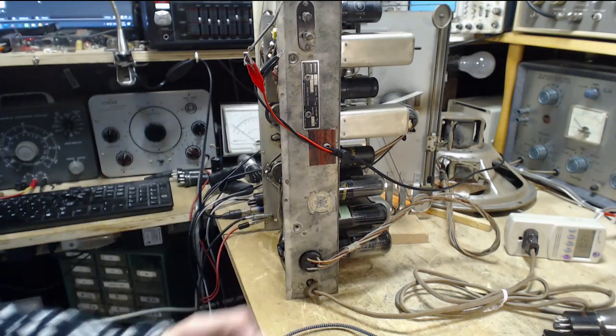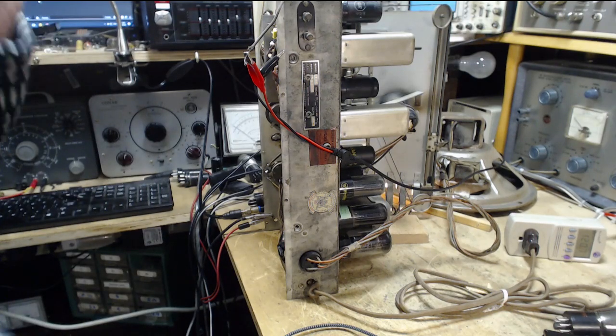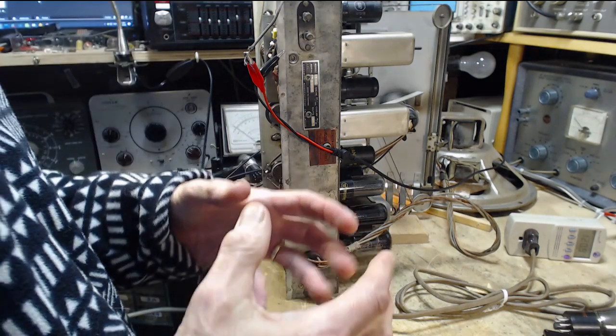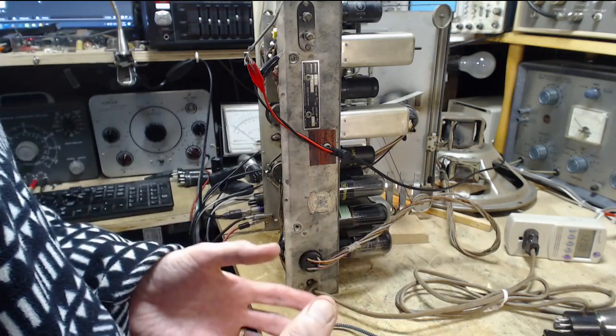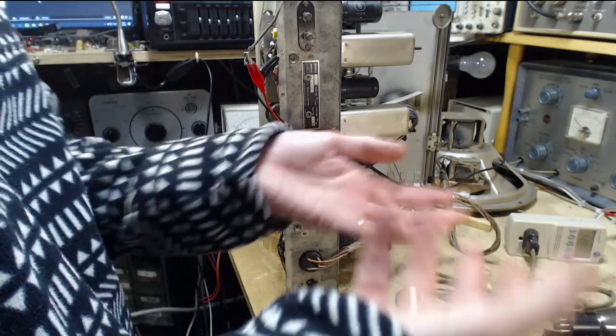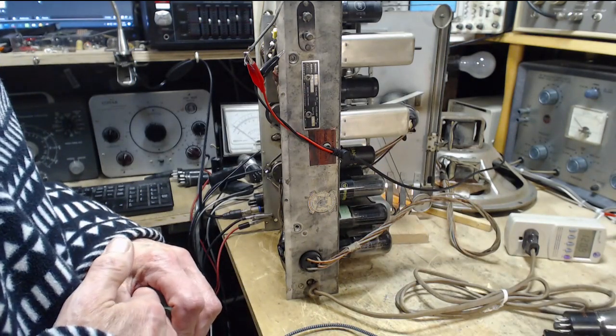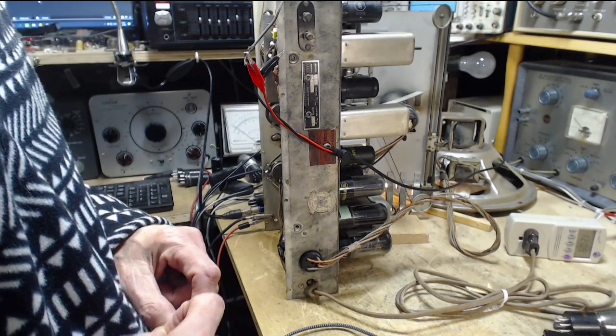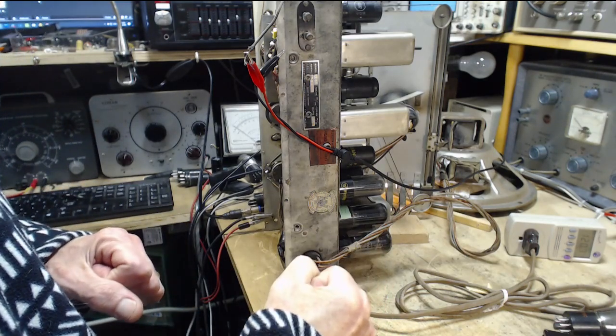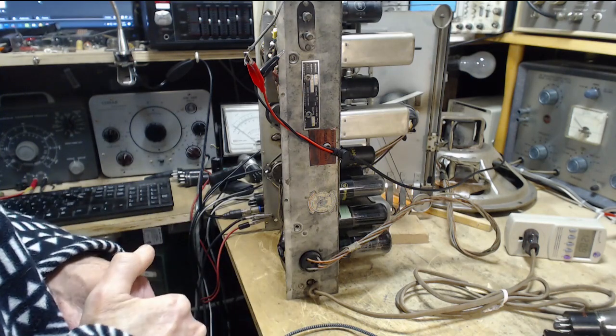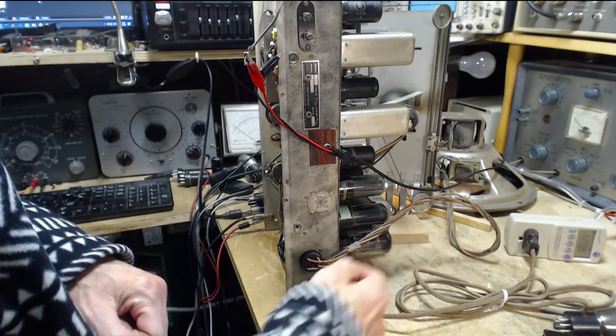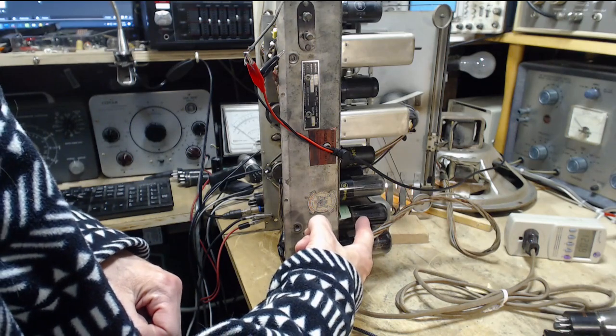And what do you need the hot tube for? You need a hot tube to heat up the cathode. The cathode's ability to emit electrons gets higher and higher as you make it hotter and hotter. Quite intuitive, isn't it? So if you have a tube that needs to really push the current through, you need a hot cathode. And that's what's going on with these three tubes. Well, two of them anyway. What's going on with this?